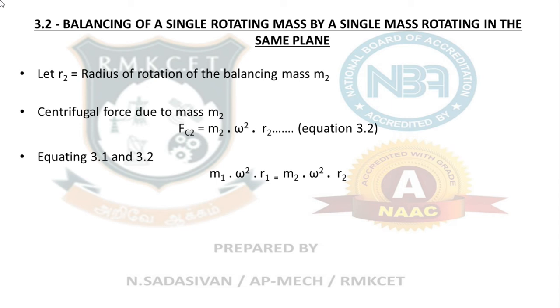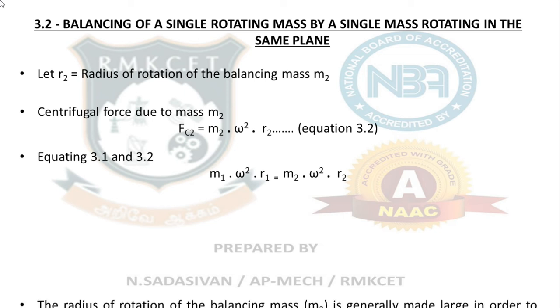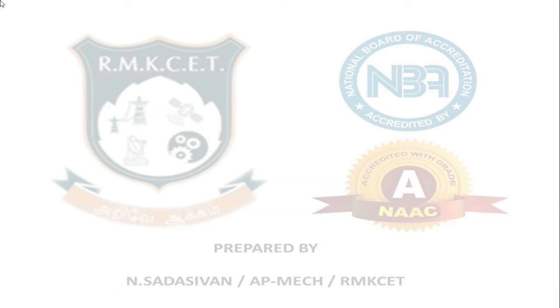Okay. So when you want to balance a force, you have to find the vector sum of all the masses. I mean here in a static balancing case. Vector sum of all the m omega square r involved, and then find the resultant magnitude and direction, and you have to oppose that with your balancing mass. So that is the idea. Centrifugal force is the most important thing here.